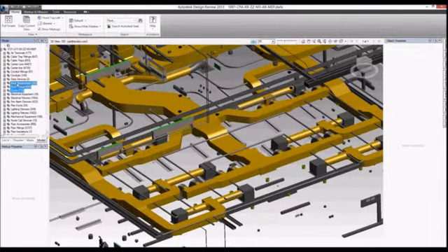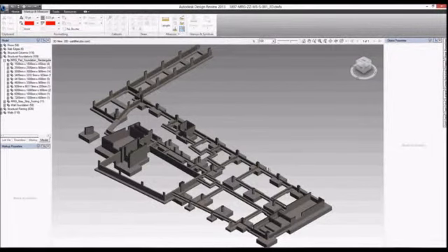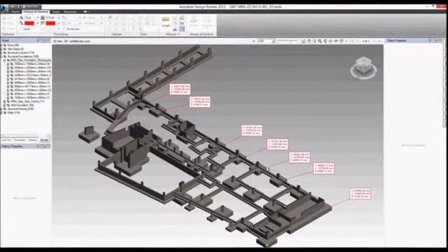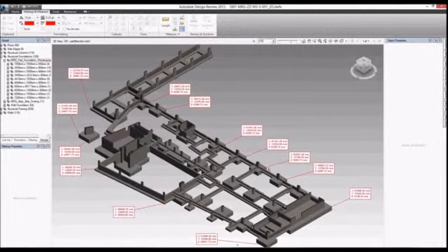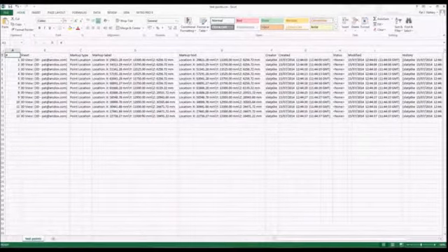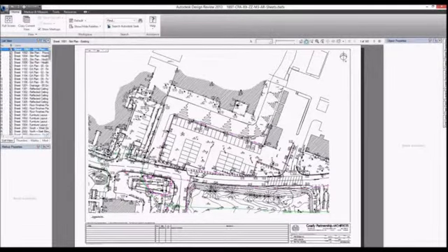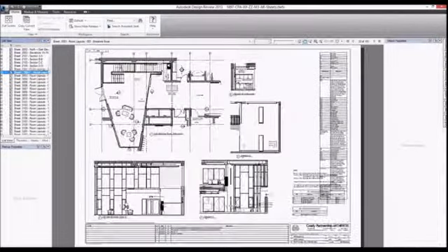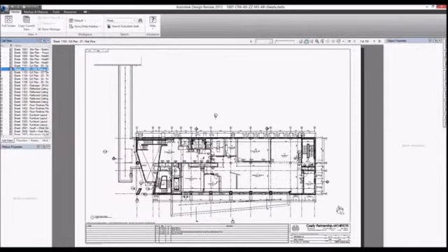The dimensioning tools include point location, in this example used to identify coordinates for the concrete foundations. The markup can be saved by exporting these to an Excel spreadsheet where they could be sorted and extracted for use in other software. Drawing list or thumbnail views allow you to select from a set of 2D sheets. Elevation, section or callout tags act like hyperlinks to allow easy navigation between sheets.